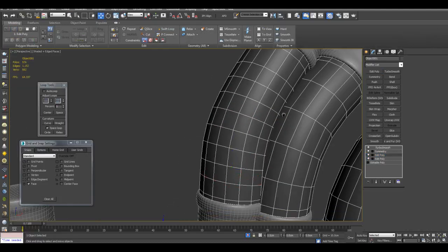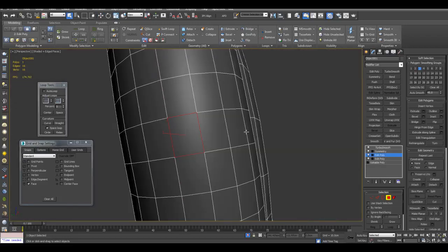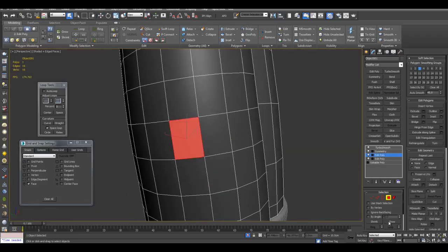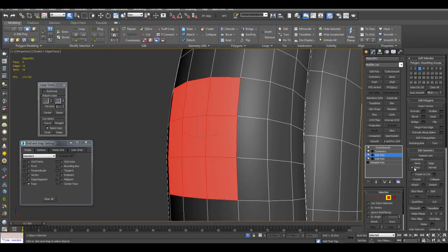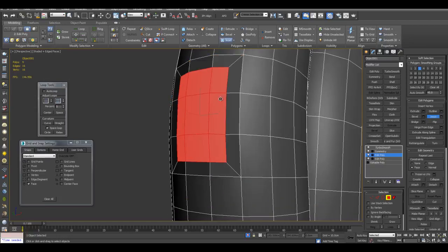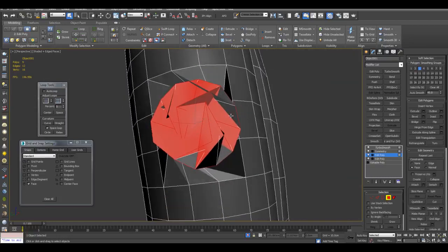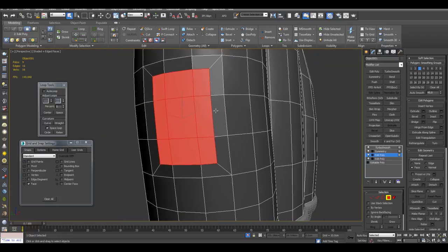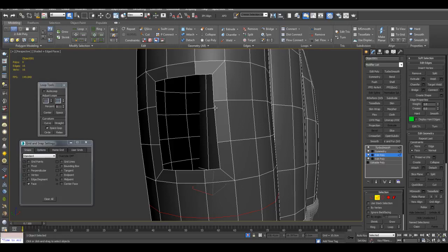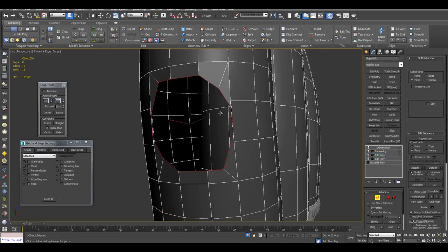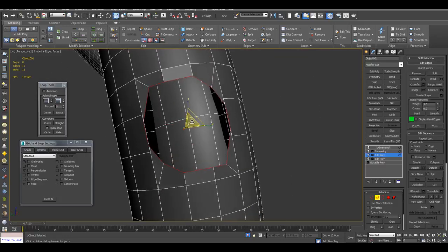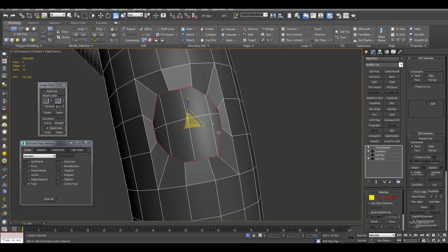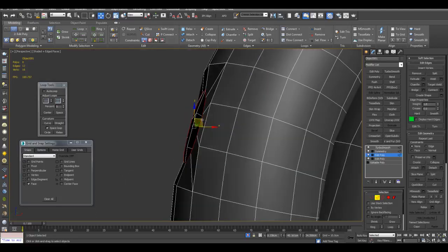Right, let's say right here, new Edit Poly modifier, and now I can select polygon here, grow, turn on face constraints, inset, then use regularizer to make this spherical. If you get this result right here, just press Ctrl Z and delete this, switch to edges, double click, and then regularize again. Scale inwards and regularizer. There we are.